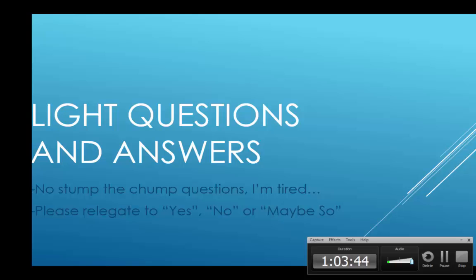So does that help a little bit? Well, we kind of dabble in all of those, and so I was wondering if there's any advice. Yeah, I would personally make it the configuration name and then make sure that the checkbox is checked that says use the configuration name for the description or for the part number for the bill of materials at that point. Okay.